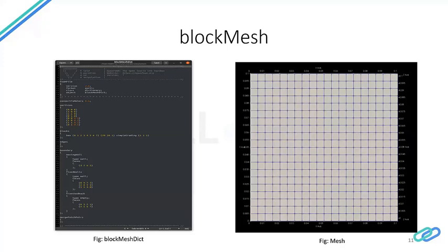Here, the geometry is made for a rectangular block, and as we can see here, a function that we refer to is convertToMeters. What this does is it is for unit conversion. OpenFOAM inherently adopts SI unit systems, so length is considered in meters. And right here, we can specify the conversion factor. For instance, for inches, you can just write 0.0254. And right here, we are using centimeters. Here we specify our vertices for our geometry. And as we can see, the Z direction is also specified.